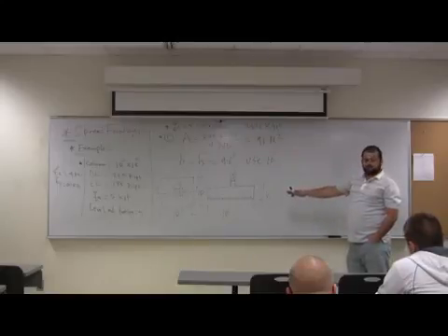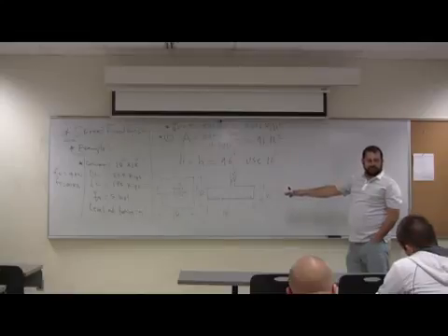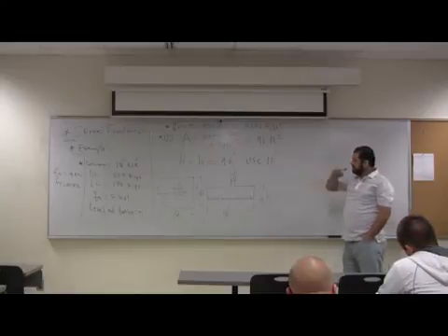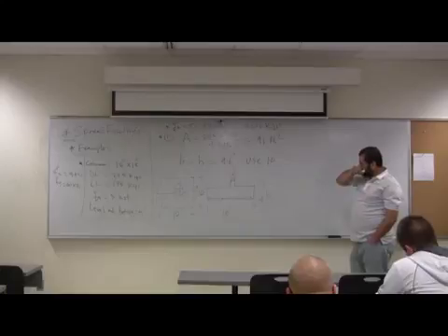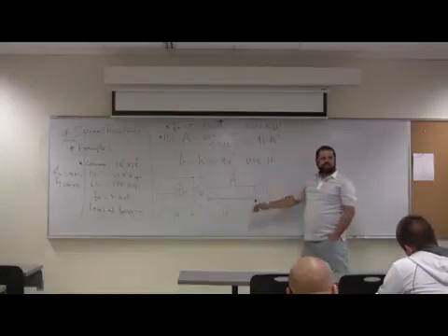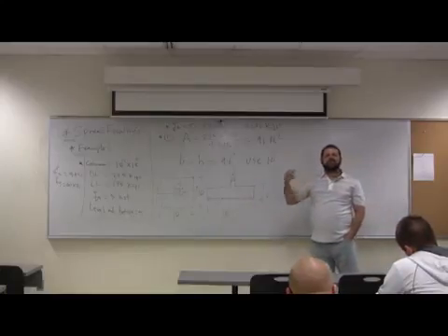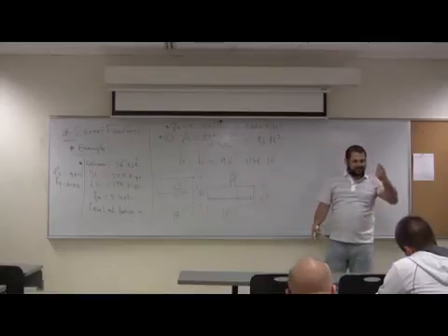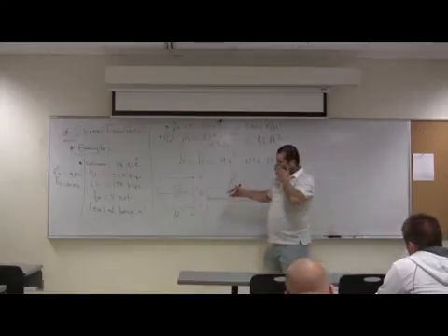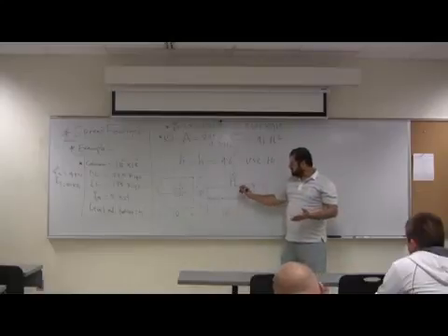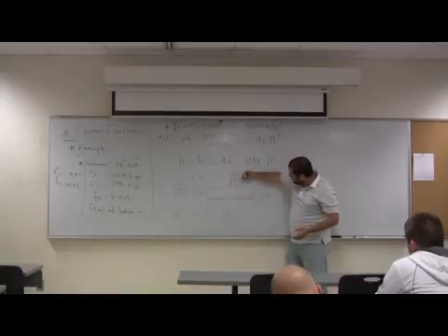Now, for this one, they have good questions about the foundation. Not easy questions, actually. Look, there are 2 types of shear in the single column footing. This is the hard one. There is the shear at D from the face of the column. Right? So how much is the distance from here to here?